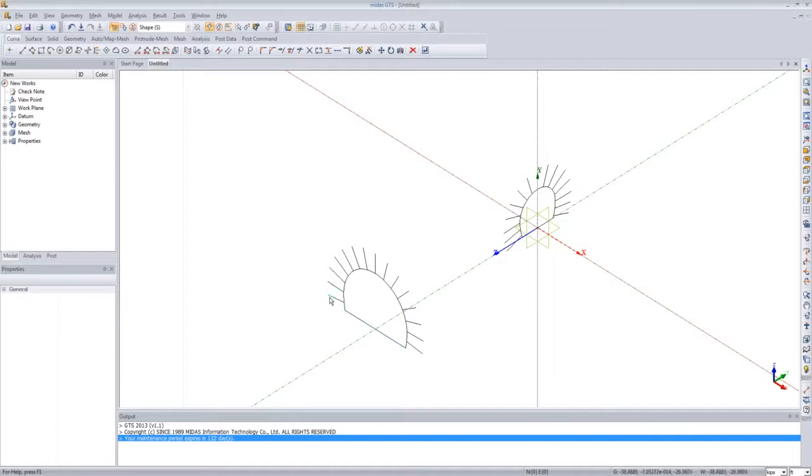So now what we need to do is create a different geometry set for the rock bolts. So open this, here's the work tree menu. Open the Geometry tab, and then you'll have all these options. We don't have any of these things created yet, but we can create a new geometry set. That way we can select certain pieces by sets for convenience. So right-click on Geometry Set and select New Geometry Set. Now you have the option of creating a new set. So let's rename this Main Rock Bolts.